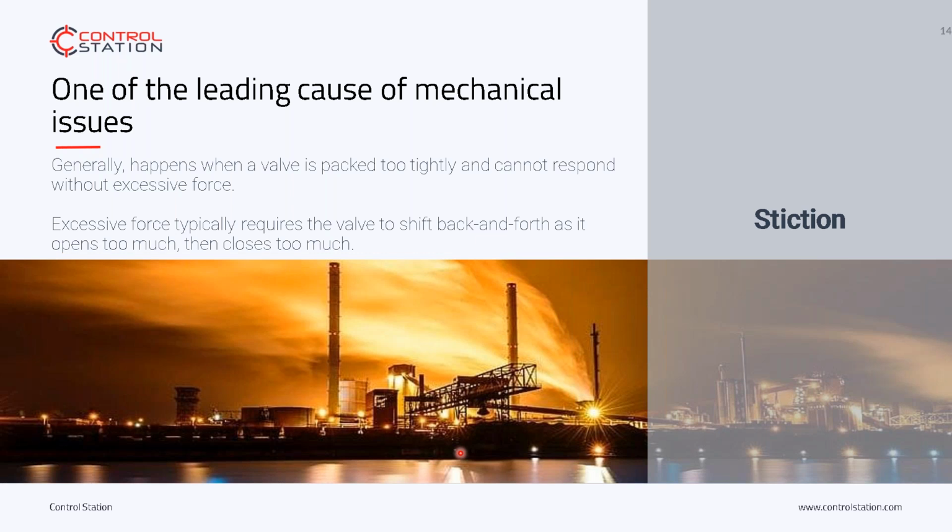If you have an adequate, accurate, and efficient maintenance program, that you repack those valves every year, whether they need it or not, you can avoid that. But again, it's a very costly addition to your process, in that you're changing your valves, or at least doing maintenance, whether they need it or not, rather than doing it on a scheduled or a condition-based system.